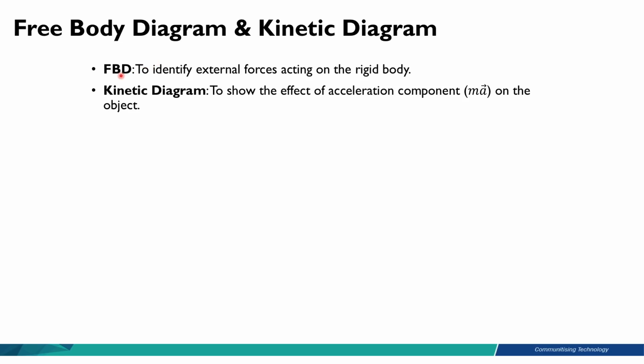So what is the difference between the free body diagram and the kinetic diagram? The free body diagram is drawn to identify external forces that are currently acting on the rigid body, whereas the kinetic diagram is a diagram that shows the effect of the acceleration component ma on the object.